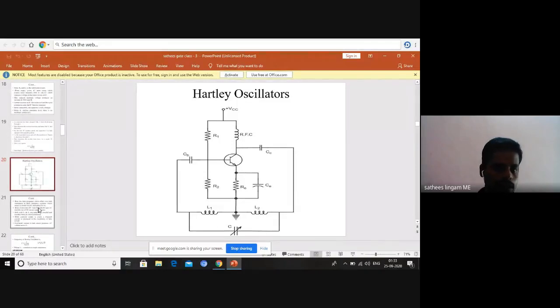Okay. Here, as usual, the CB is used as the coupling capacitor. We can also call it a blocking capacitor. On the input side it is a blocking capacitor, because it is used for blocking the DC content. The same capacitor is used on the output side as a coupling capacitor, because it is going to couple with another circuitry. So if it is connected on the input side, it is called a blocking capacitor; if it is connected on the output side, it is called a coupling capacitor.